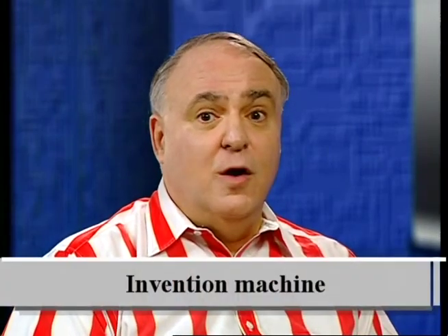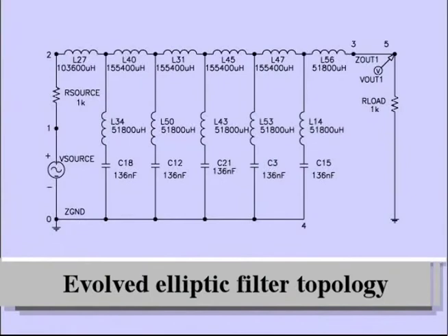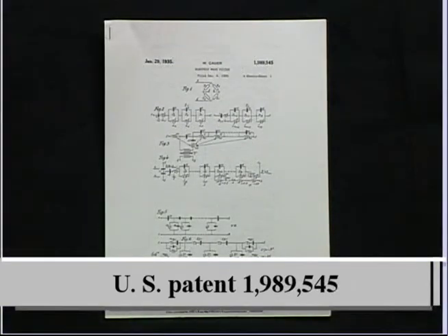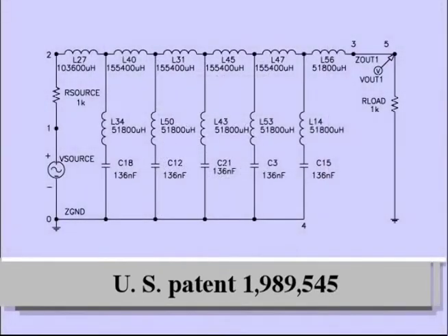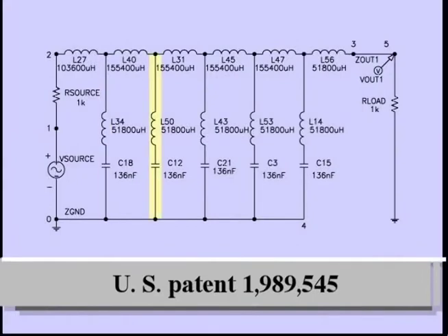Because genetic programming is not encumbered by preconceptions that limit its search to well-trodden paths, many genetically evolved solutions duplicate the functionality of previously issued patents in novel and creative ways. This suggests that genetic programming may be useful as an invention machine. For example, on one particular run of the low-pass filter problem, genetic programming rediscovered the elliptic filter topology patented by Wilhelm Cauer, with 5 shunts that were constructed by multiple invocations of an automatically defined function.